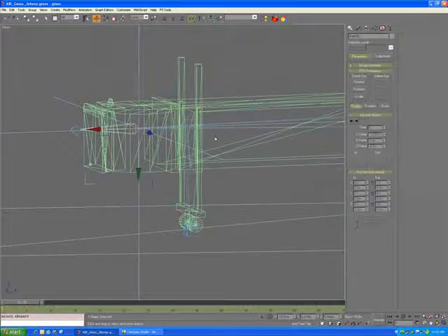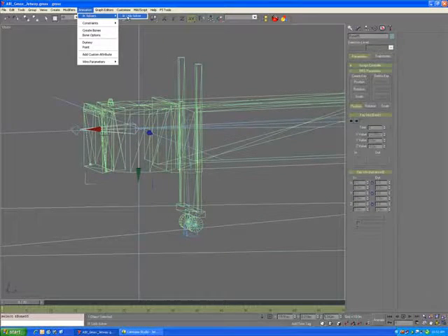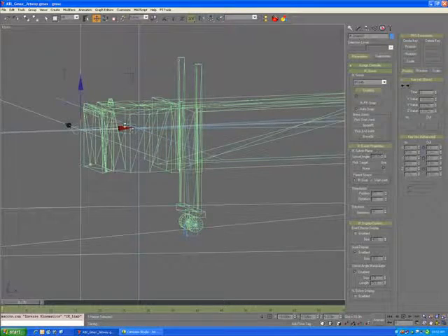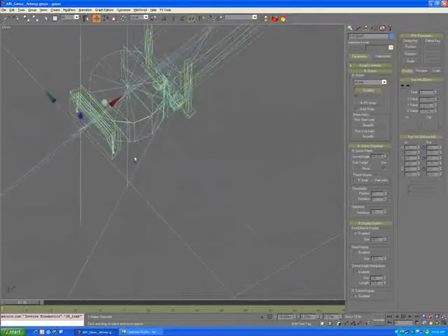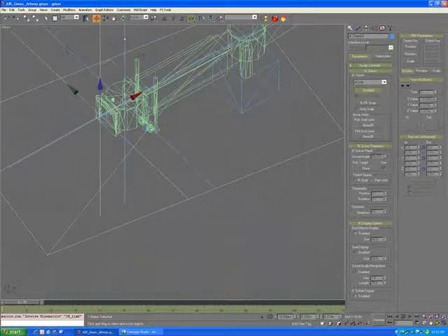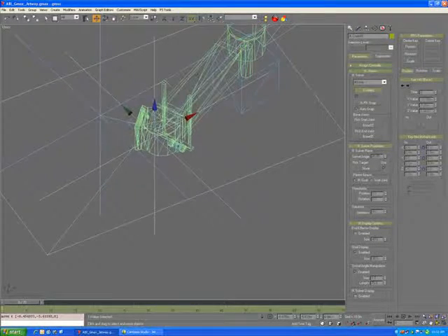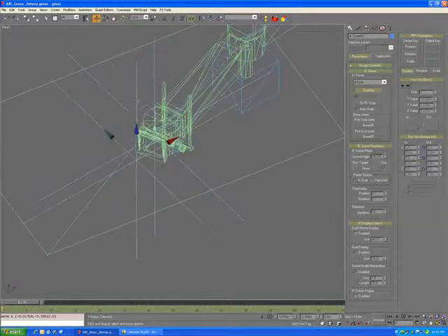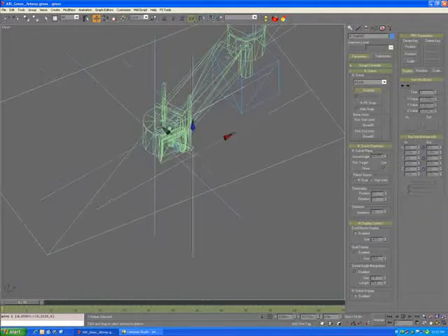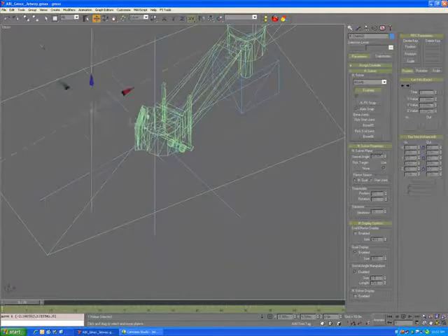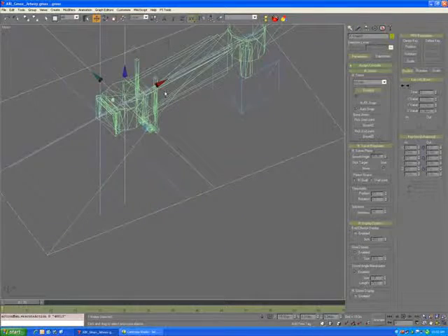So then the next IK handle you want to do is you select this bone there. Once again, IK solver, limb solver, and then you go to this little one at the end here, and now you have 2 IK handles. You have one to control the main. So if I move there and then I grab this other IK handle and move it here, you can see how it would attach. And once again, you see the limits. It won't go any further than its limits are.